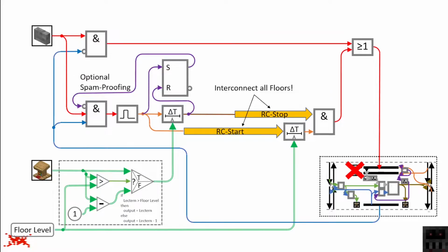And what the circuit here does is, it broadens the range from 1 to 15 to 0 to 15 and makes a jump at the current floor, or the signal strength that represents the current floor. So I'm not able to address the current floor for a remote call, which wouldn't make any sense at all.